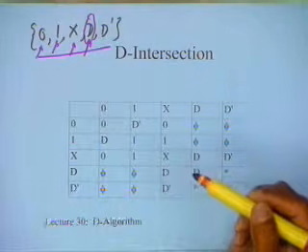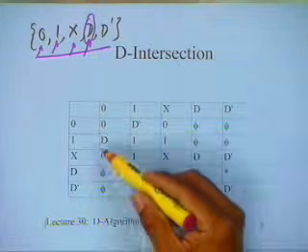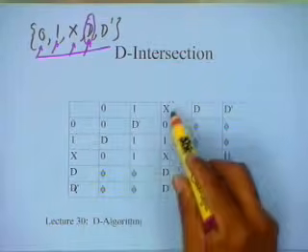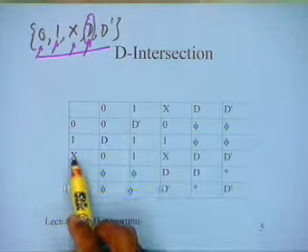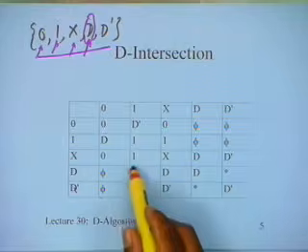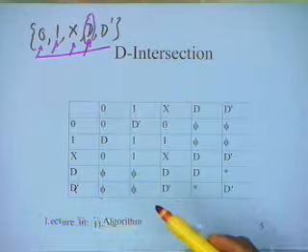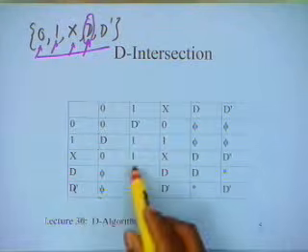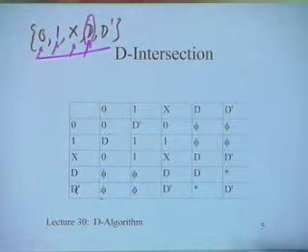So, 0 and 1 is giving you a D complement, 1 and 1 is giving you a 1. When it is do not care, you essentially get what you have written over here: 0 gives 0, 1 gives 1, do not care gives do not care. So, this is going to override do not care. Similarly, if you look at this particular row, 0 gives 0 and do not care gives 0, 1 and do not care gives 1, and so on. These are not specified, and I should never intersect in a manner that I do not know what the value is going to be. So, basically you should avoid intersecting D with 0, D. You are not allowed to do that, because you do not know what is going to happen, it is not specified. All these are not specified, all these are also not specified.